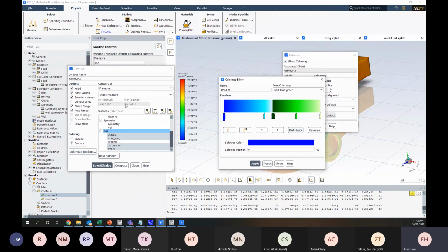And we want to know our maximum and minimum, just so we can get a ratio. Maximum pressure is 90. You can see that in here. I might not use the global range though. Yep, still 90. And the minimum is -491. So I just want to know where the 0 point is. It's about 15% from the top. So this white one will go to 85.